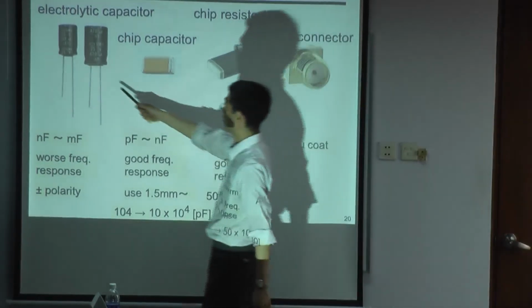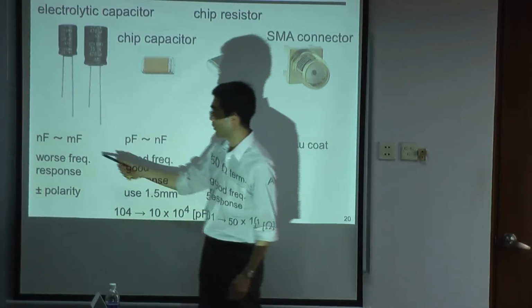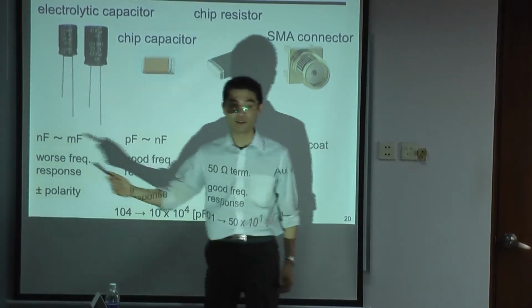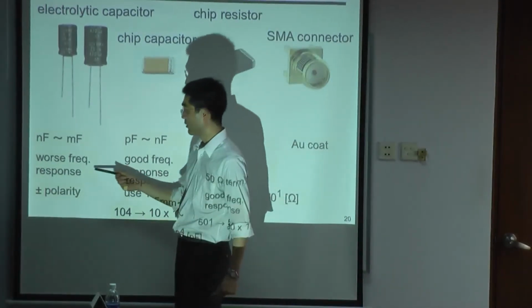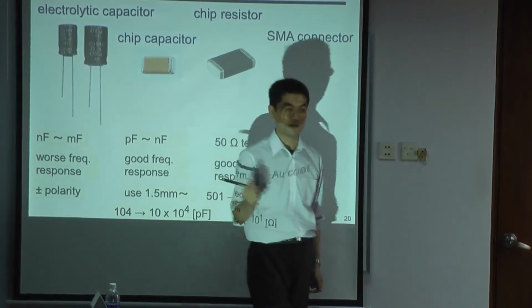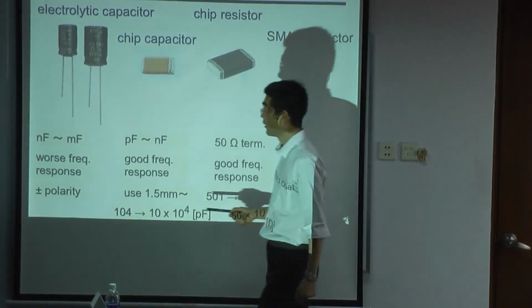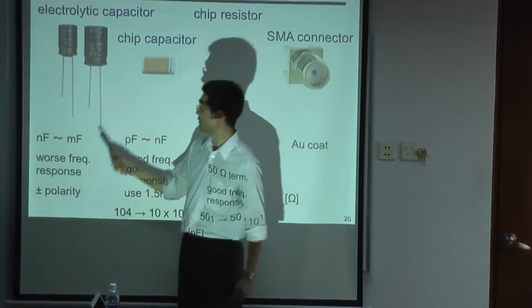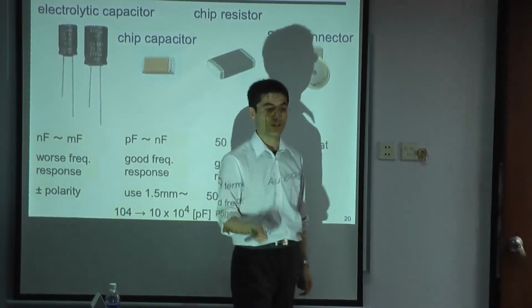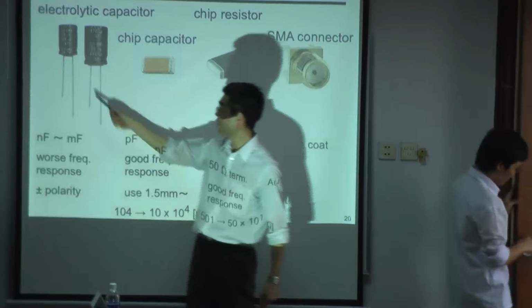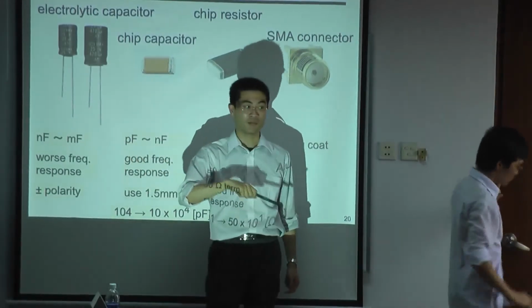For this type of capacitor, we have large capacitance, from nanofarad and microfarad to millifarad. But the frequency response is not good. And also we have a polarity. The longer terminal should be the plus terminal, and the shorter terminal should be the minus terminal.